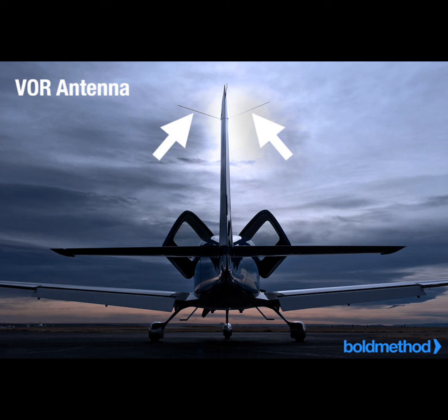Describe the proper method of routing coax cables from the antenna to the receiver. Most direct route. Secure every 2 feet. Route separately from other bundles. Don't tie to other wire bundles. Keep bends under 10 times the cable diameter.